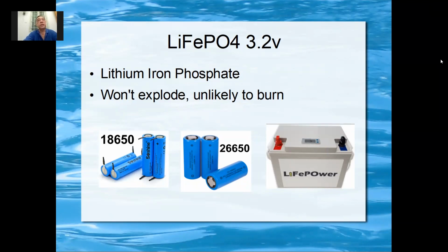Sometimes they can even use this to replace the lead acid battery, which I did not show here. Sometimes people call it an AGM battery, which is something like lead acid, except that the acid in this case is a gel. So it will not flow left or right, and you can turn it upside down and it will still work. This is just an improvement in the electrolyte, but basically the anode and cathode are all using lead, so it's very heavy.